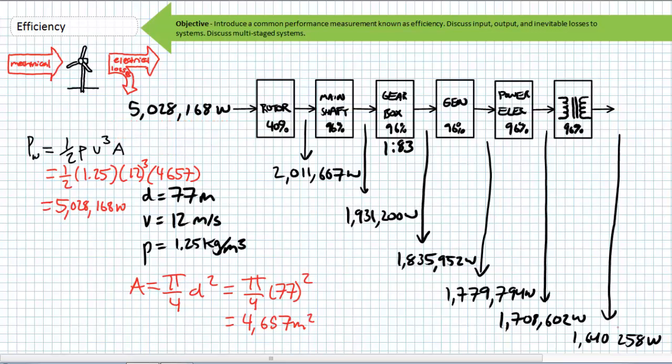This roughly 5 megawatt input, however, is subjected to the most critical of efficiency measurements regarding wind power, the Betz limit. The Betz limit is the theoretical maximum of roughly 59% that can be extracted from a column of wind, beyond which the wind would just stop moving. Even well-designed modern wind turbines have not even come close to the Betz limit. A respectable modern wind turbine might be capable of extracting only 40% of this oncoming wind power and converting it to useful rotational mechanical energy.